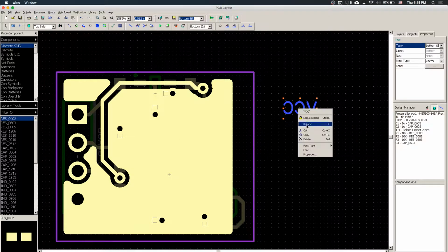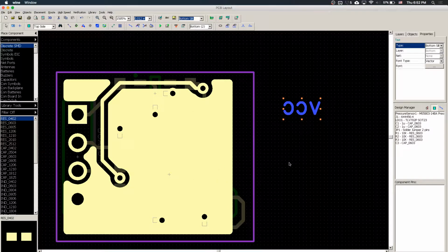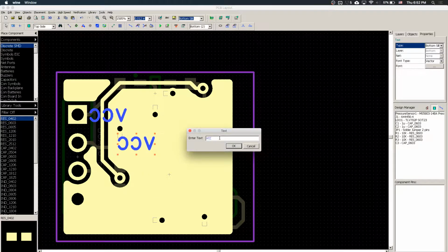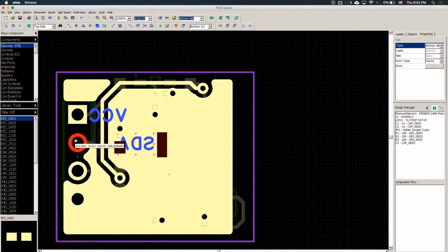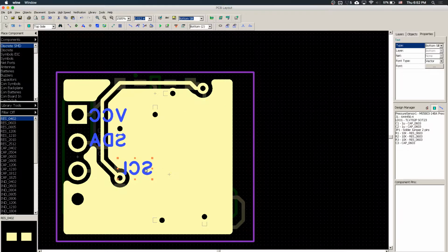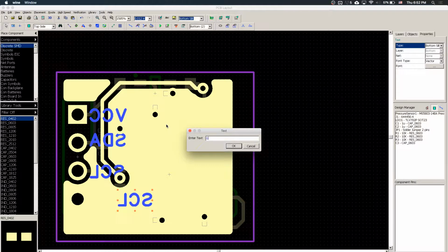and place it as bold. And place it next to the VCC pin, like that. And I'm going to copy paste it. It's kind of weird how they change text. You have to click the VCC label, and then you can change the text for it. So this pin will be SDA, and this is our SDA pin, and SCL. And ground.